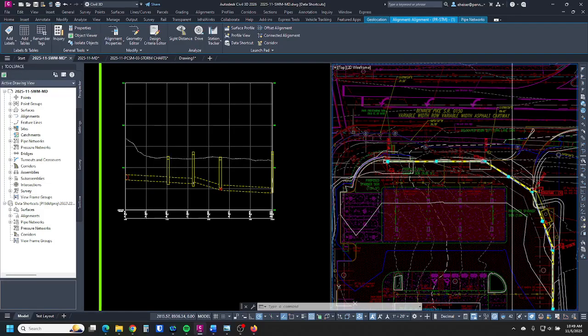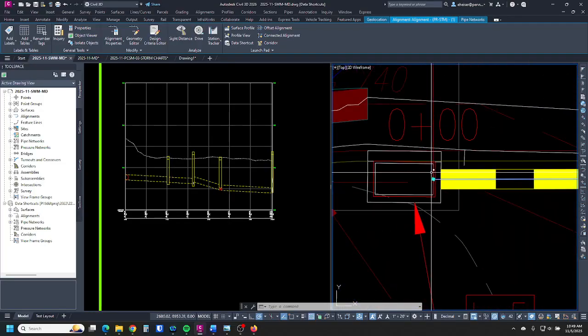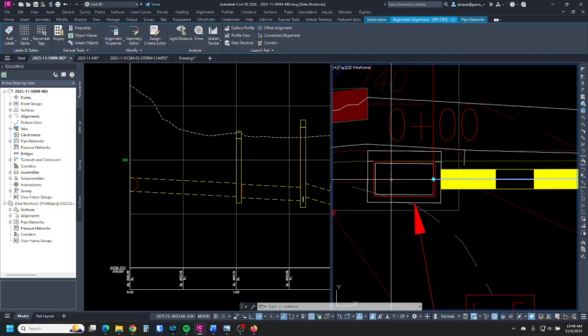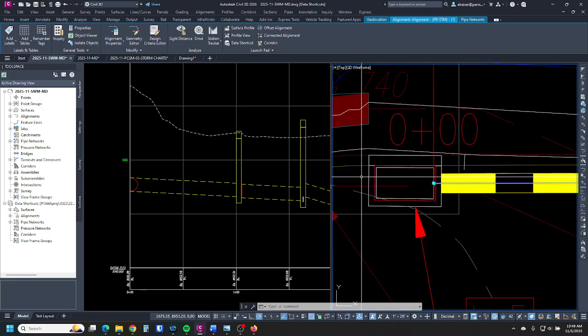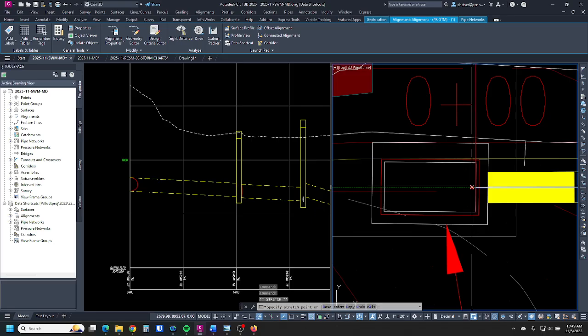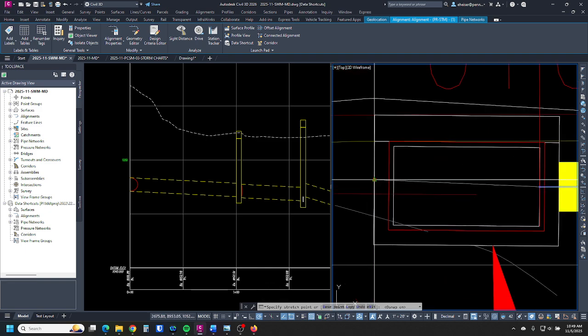If you were going to use this option, what I would do is modify the geometry of the alignment. You'll also notice at the end, it started the profile at the invert out, so you can't even see the structure here. The way to modify this to make it a little more usable, even if this is just a working profile, would be to add some extra PIs. So the first thing I would do, we'll do this one real quick, is drag the endpoint of that alignment,